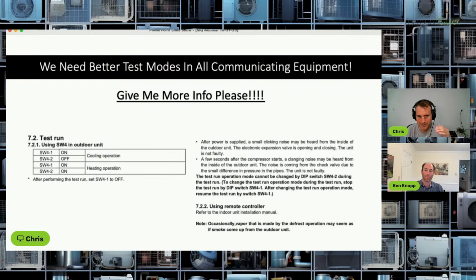And I don't mean full cool where I can only know that the fan isn't going to modulate on the indoor unit. I mean full cool where I can tell that the compressor is at 100% capacity for cooling mode and the indoor fan, right? I need to know that stuff. So anyway, that's my rant. I wish it wasn't the way it is. But anyway, all right.